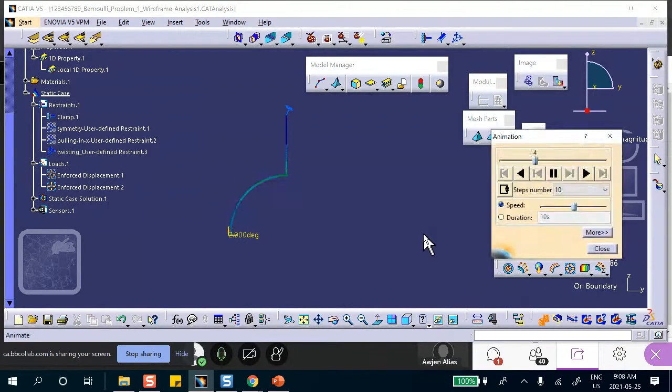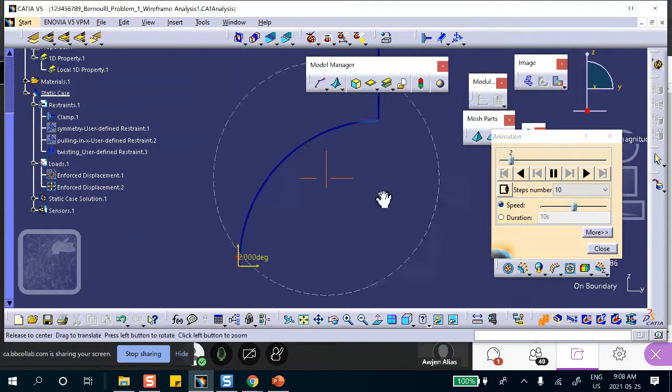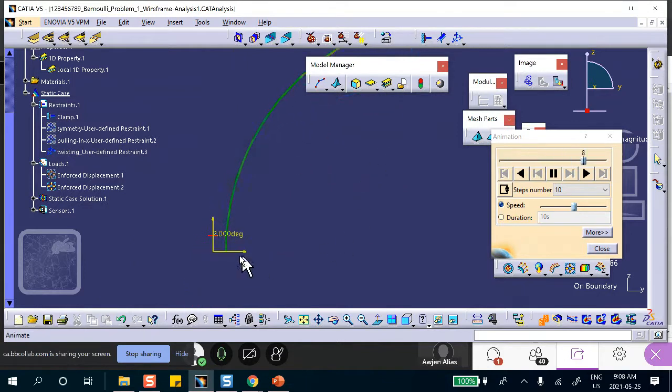Right there. I think that makes sense if you look close by. The fact that it's coming towards you means that it does not go up and down. Remember, we fixed the Z displacement because of symmetry. Remember, that's the first thing that we did. No displacement in Z. It doesn't go up and down because this is a plane of symmetry. Exactly the same thing must be happening at the bottom. It cannot go up and down.